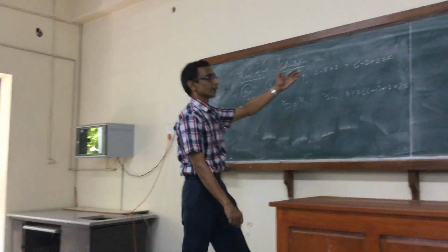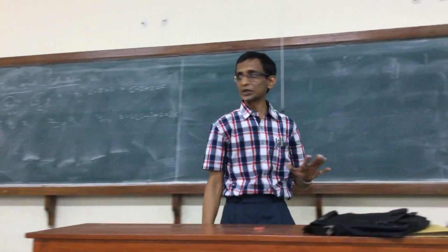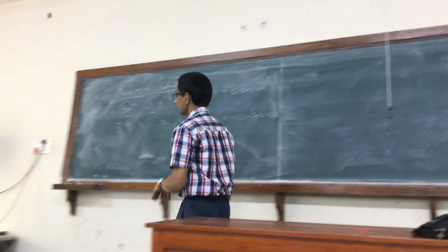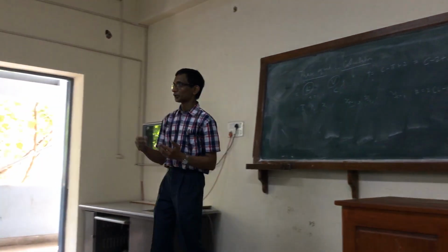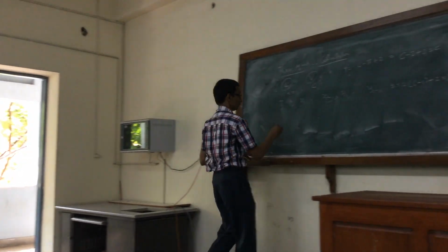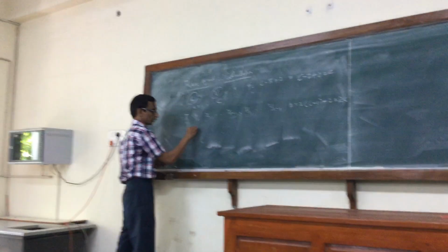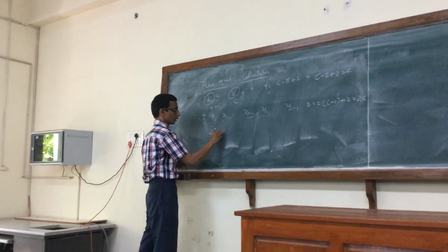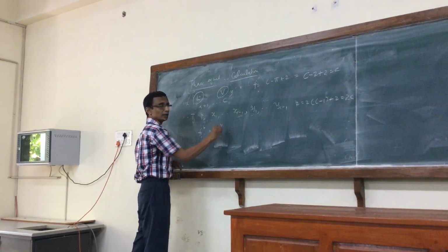C is the number of degrees of freedom, so I must have C equations. C equations, they are the equality of chemical potential. I am going to represent them here by the equality of fugacities: fi of L is equal to fi of V.